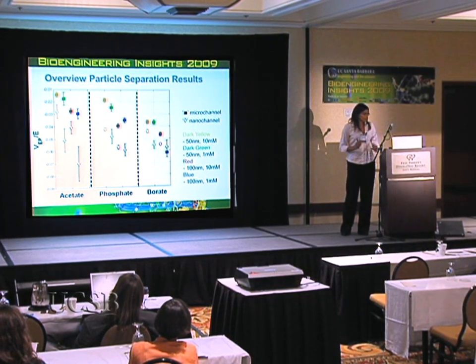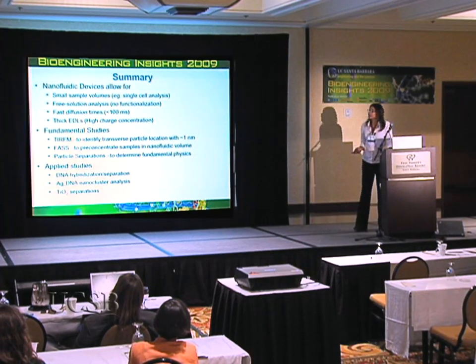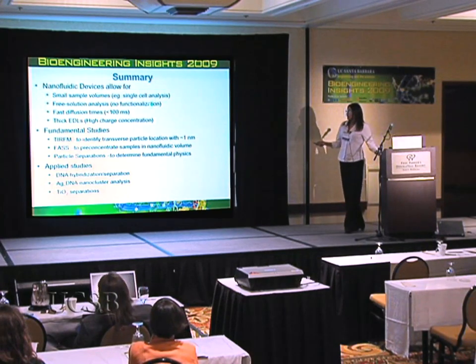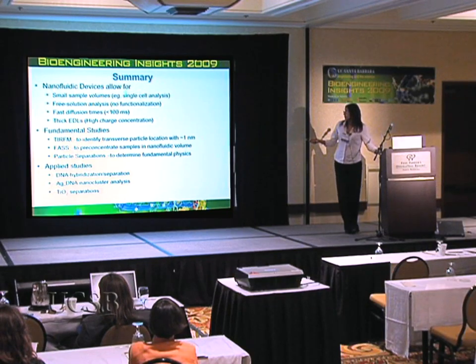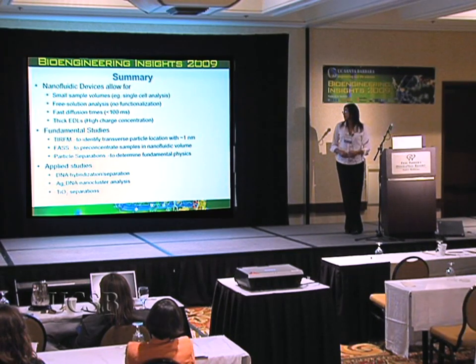So in summary, nanofluidic devices allow for the fact that we can use small sample volumes. We can do everything in free solution. We have very fast diffusion times and very thick electric double layers, which allow for these neat physics to occur. We've been working on fundamental studies to identify what's important, what are the important physics in this scale, including total internal reflectance microscopy to identify transverse particle locations within 1 nanometer. Field amplified sample stacking, the pre-concentration technique.